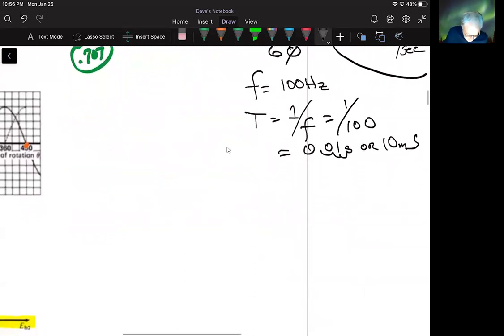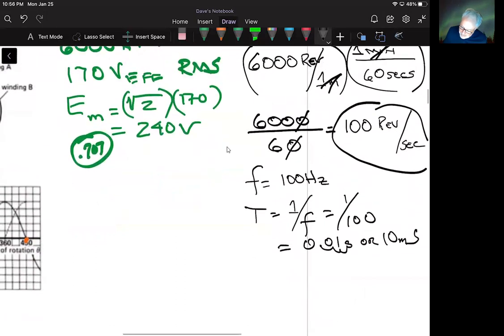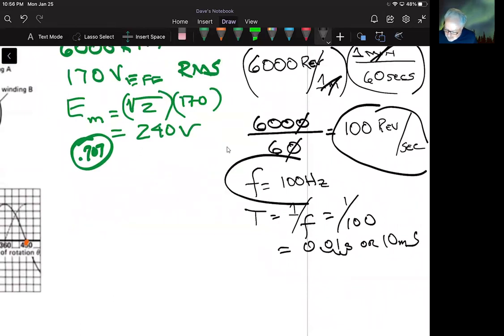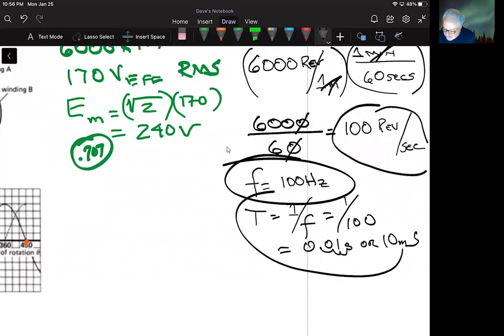So I figured out the frequency first here, 100 hertz. That's the output frequency that we would have. And then he calculated the period first, but I want to give you 2 different looks at it. One is the inverse of the other, so they both work. And then the last thing he says is, how much time would occur after a rotation of 90 degrees?